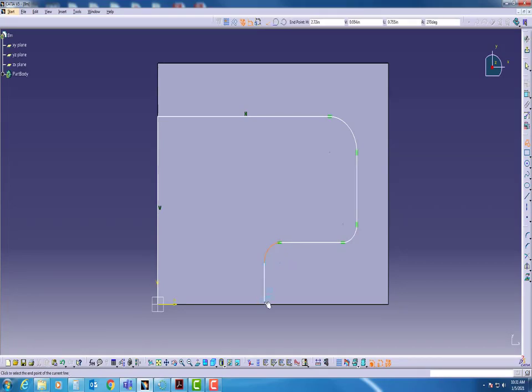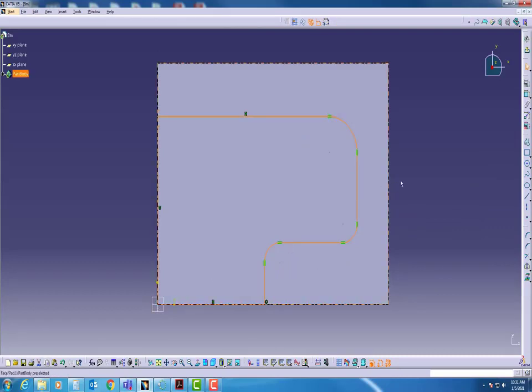And then I'll simply come down until you see my dotted line pop up. That means I am horizontal. And then I'm going to close the curve. A lot of people will stop here and their curve is not closed. If that happens, you can simply click on your geometry again, click on this point, and then close it. So you can see that it is closed.